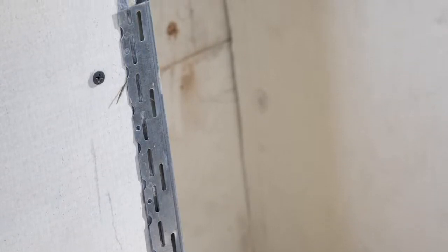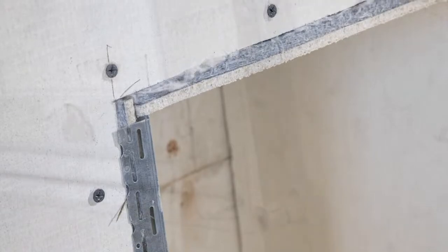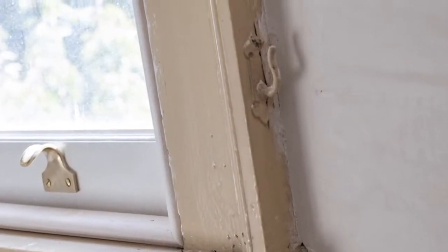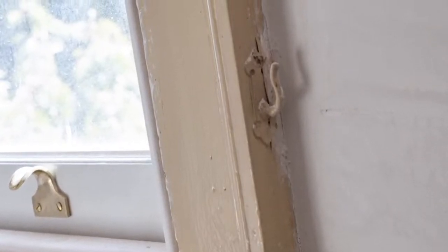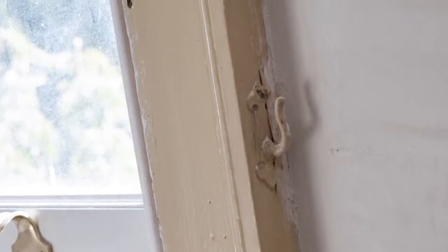The property in Bath was built in 1818 and has been in his family for 101 years, since 1919, so it needs some serious upgrading. The project was initially specified utilising 100mm of conventional insulation, necessitating moving door frames and rebuilding window reveals, as well as a fair amount of lost floor space.